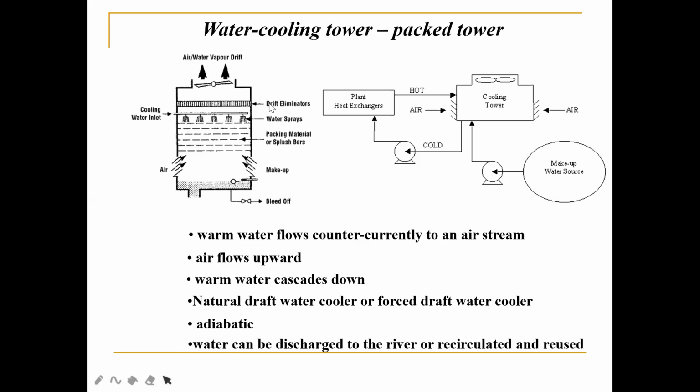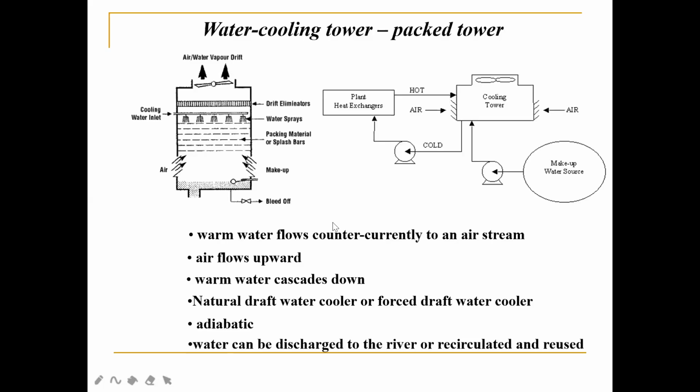In this diagram you can see that warm water flows countercurrently to an airstream. That means the warm water will be sprayed down into the packing, and you will have air flowing upward because you want the air to be in contact with the warm water flowing down.